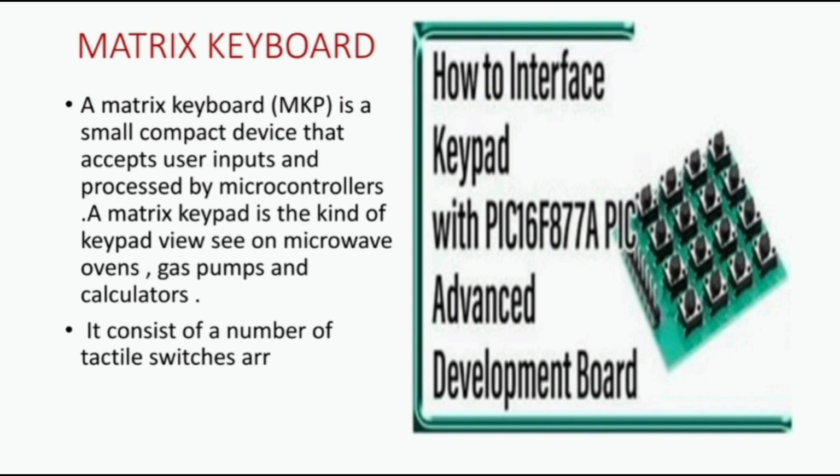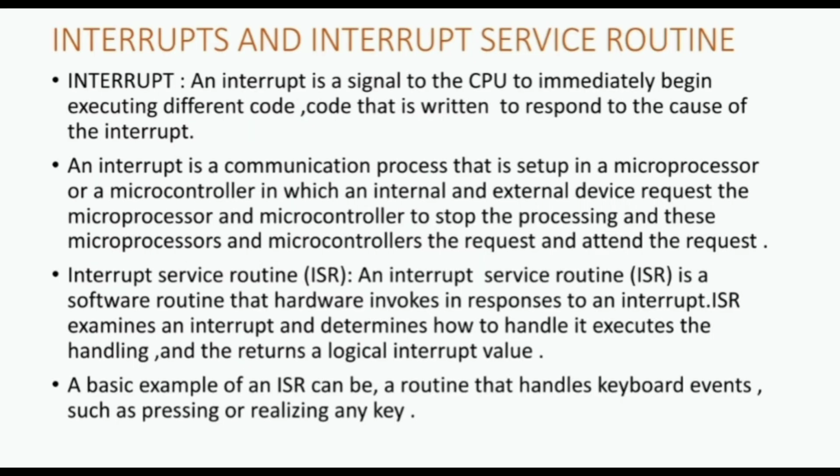Coming to the next one, matrix keypad. A matrix keyboard is a small compact input device that accepts user inputs to be processed by microcontrollers. A matrix keypad is the kind of keypad you see in microwave ovens, gas pumps and calculators. It consists of a number of tactile switches that are arranged in a row and column format. The advantage of matrix keyboard is that the use of it will allow the programmer to reduce the number of pins to be used.